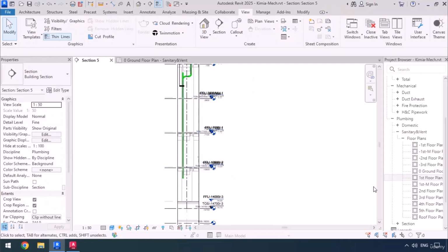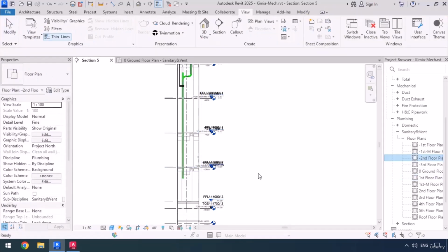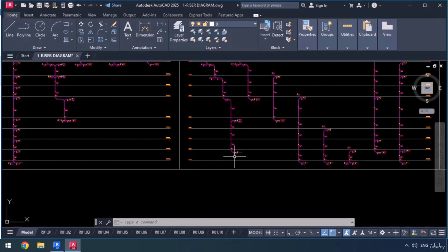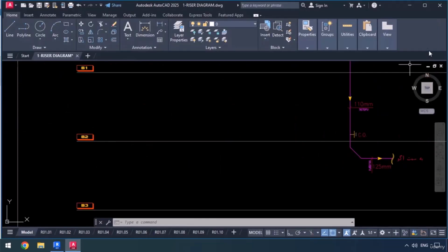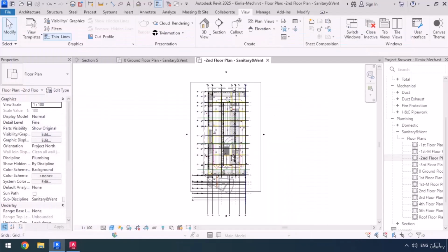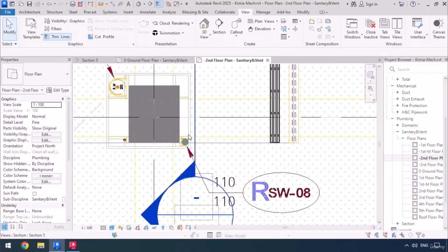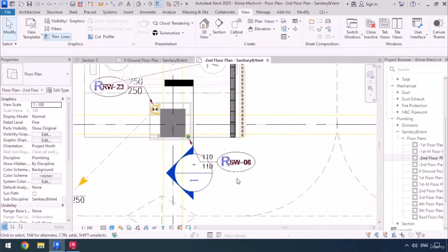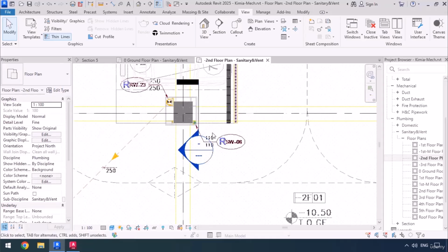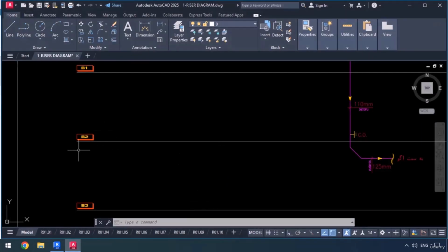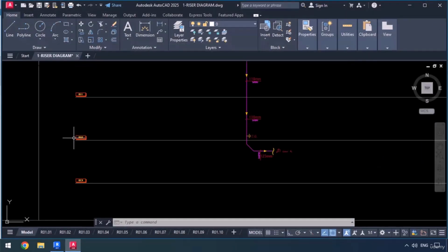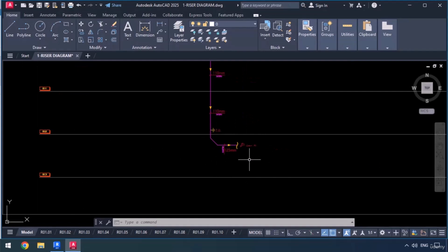Now let's head into the -2nd basement's floor plan, and also we saw that in the riser diagram, the pipe was supposed to end there. So the riser is located here, and as for the rest of this path, we can see that it says in this level, this riser number 8 goes further down. So there's a new contradiction here. Let's double check the riser diagram. This one says that in basement number 2, this riser ends and connects to the city sewage.